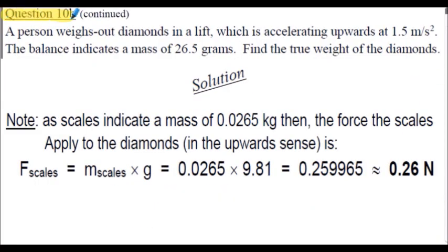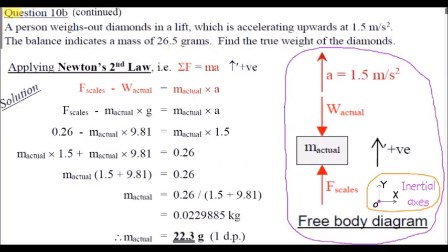Question 10b, solution continued. Here I just converted the mass reading shown on the scales into a force reading in newtons. Question 10b solution. I have actually shown a solution here using Newton's second law. This is the only question in this presentation where I actually apply Newton's second law directly, summation of the force is equal to ma. It's just for you to compare and contrast Newton's second law with D'Alembert's principle for this question. As always, draw a free body diagram here.